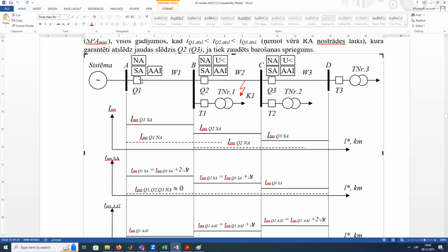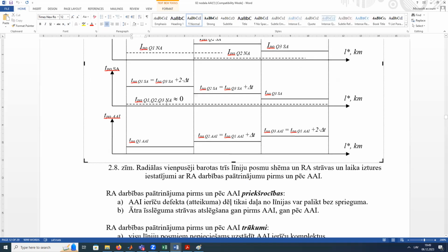Okay, of course, all of the power circuit breakers are disconnected, but for a short time. And at the end of the operation, yes, only the selective protection disconnects line number 2. But we don't have a time delay before reclosing, and we don't have time delay after reclosing. Yeah, but in this case, we need to have a very complicated protection.